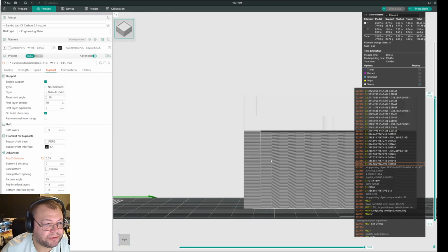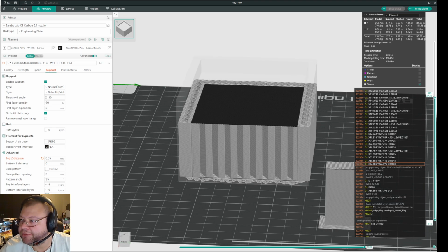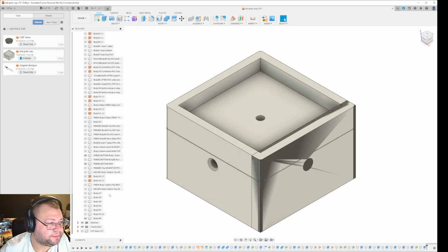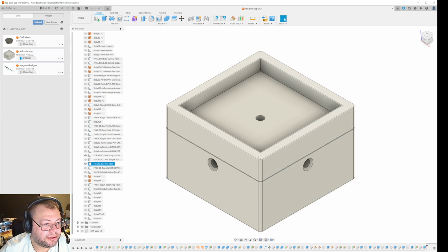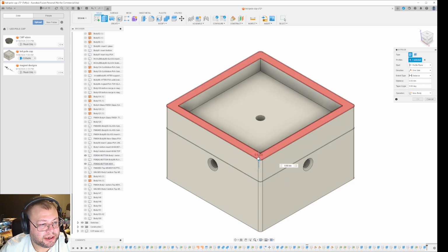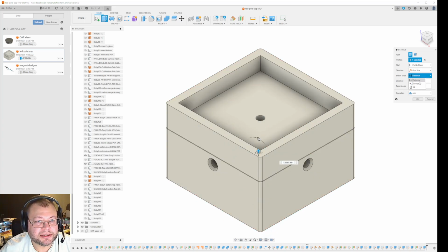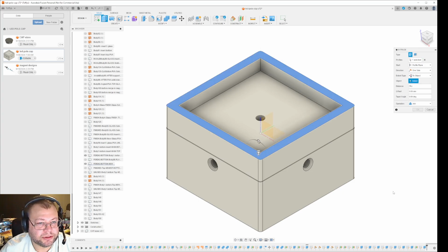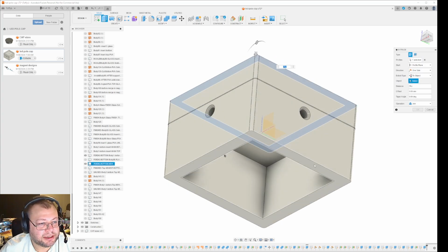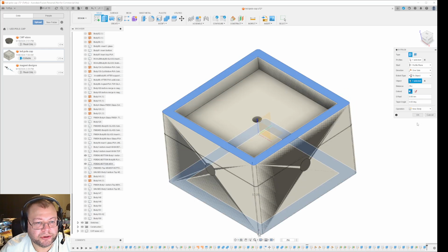Now there is another way of doing it as well. Let's say you want to section analysis all sides at the same time. You can go back and just hide that for now. I can take this extrude, with distance to object. I just want it to be exactly the same size. I'll distance it all the way down and then take new body.